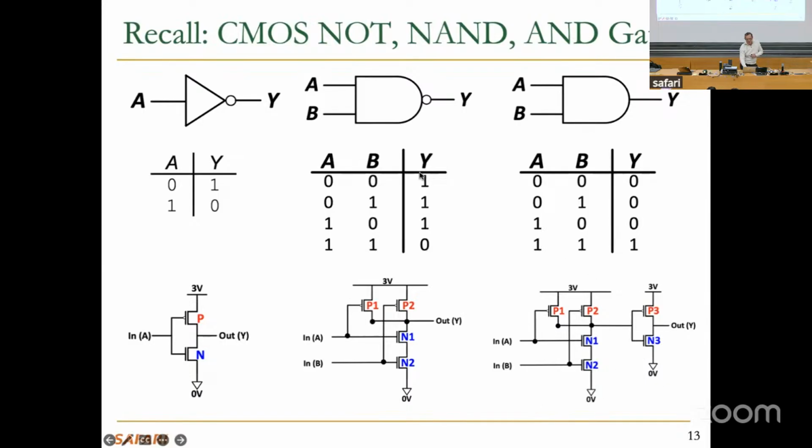So the inverter actually inverts this output over here. As you can see, this output here is the inverted version of what you get out of the AND gate. And these are the logical, I guess, module level pictures of these basic building blocks. And as I mentioned yesterday, the bubbles are always inversion. Bubble always says inversion. And we're going to have some fun with bubbles today. We're going to do some bubble pushing.